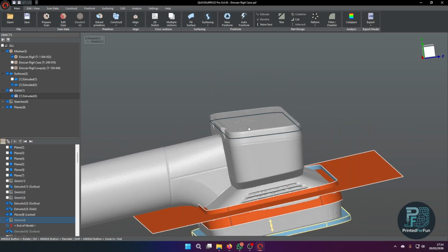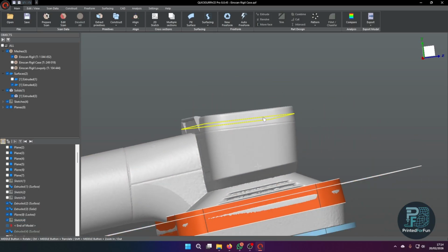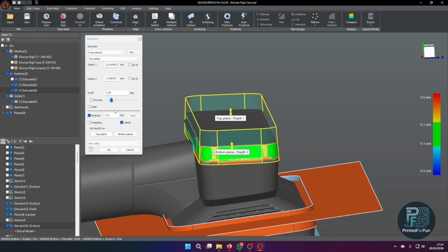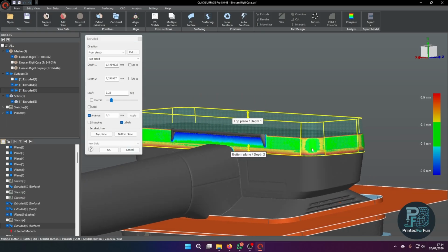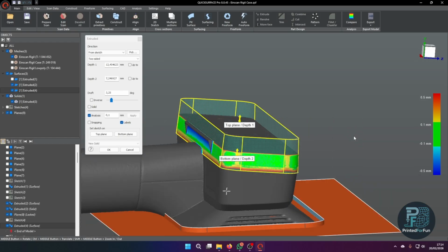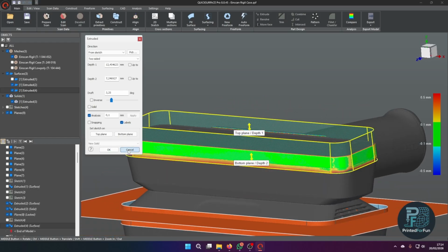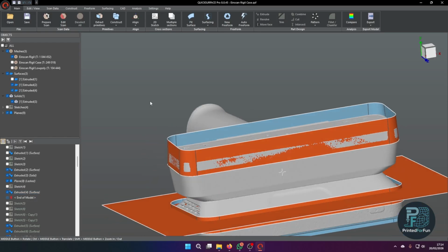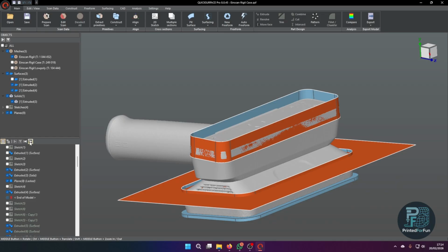Now we move to the front part. The approach is very similar here. So just one intersection sketch or offset sketch for the first draft, also with a draft angle using the analysis function. As you can see, I'm not fully within the tolerance I want to have, but in the end, it will be a TPU printed part. So chasing the higher tolerance or chasing everything to be in tolerance isn't my goal. You have to keep your senses when creating these kinds of parts and not get lost in detail.